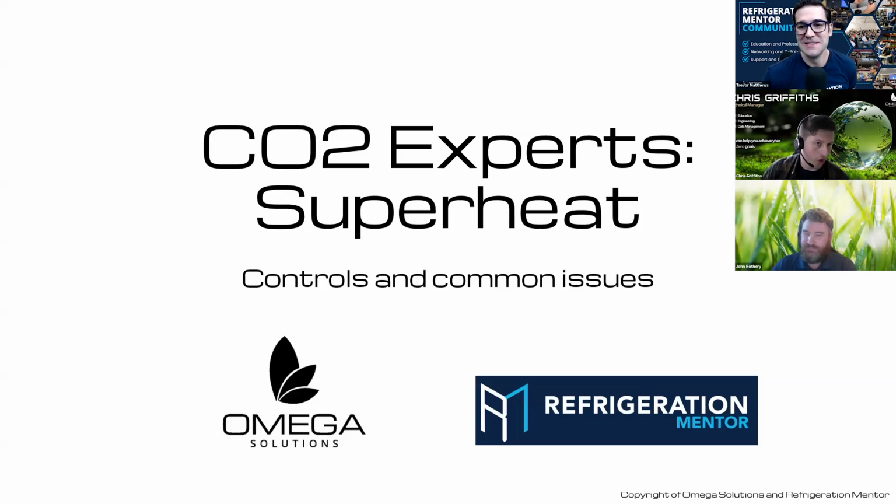We ran through some design on cold room construction, heat load calculations, condensers. Last year, piping problems. It's something both John and I had encountered several times in the past on existing installations. We worked through together to come up with solutions, identify whether it was undersized or whether it's an issue with the actual expansion valve. And to be fair, some of these issues we'll run through today on superheat can also manifest as issues in pipe sizing as well. So it's a good way of confirming what we are looking at and how to overcome it.